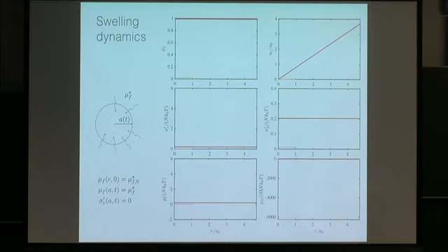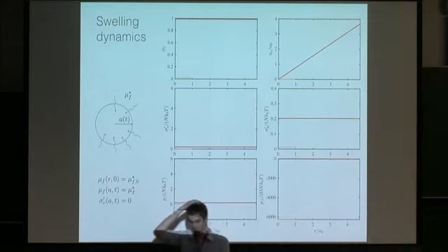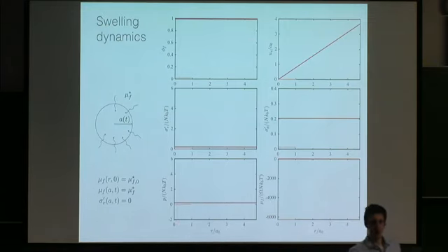So you haven't given us any boundary conditions. Yep, so they're here. So the boundary conditions are the following. Inside the gel, the chemical potential is uniform. And based on that uniform chemical potential, you can calculate everything else. And outside the gel, the chemical potential is different. So we change the chemical potential outside. And then that information will propagate into the gel, which drives either swelling or drying, depending on whether the chemical potential outside is bigger or smaller than the uniform one inside.